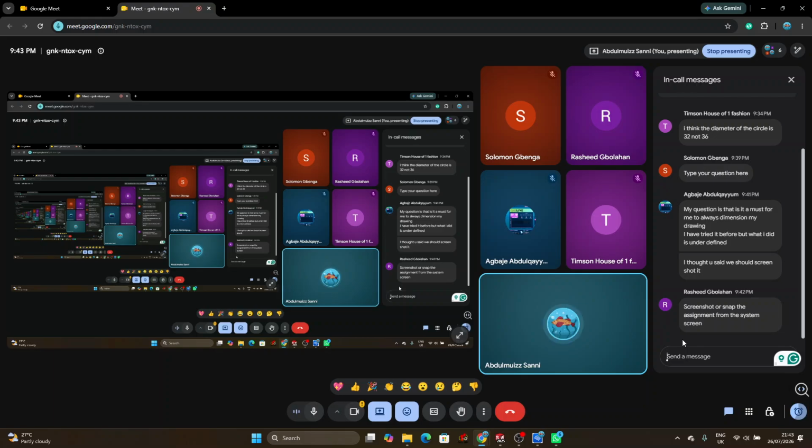Sorry, don't click on the escape key; it is just to exit any tool you are currently using. Just use your mouse to drag that sketch sideways. If it's still dragging sideways, maybe something related to a relation in that area is where you need to make it fully defined. Keep on dragging it in the direction you are dragging it. That's how you know if a sketch is fully defined or not. But it still boils down to your knowledge of sketch relations. You need to master sketch relations very well.